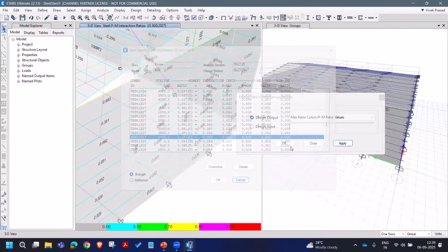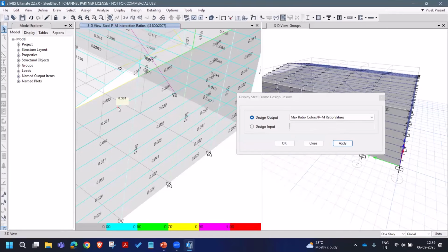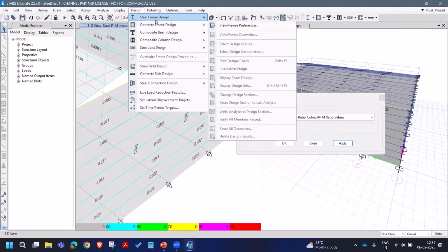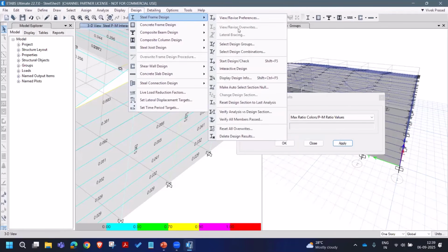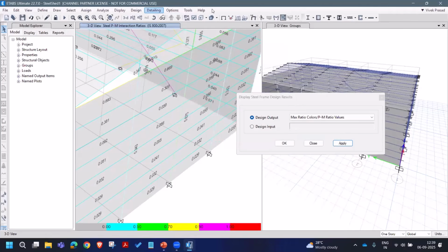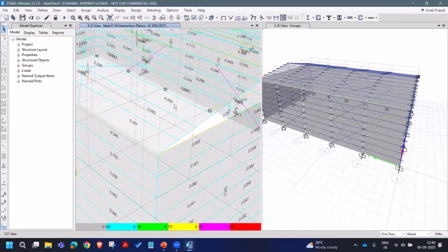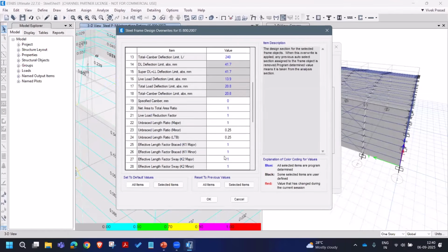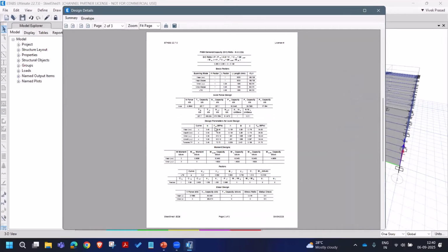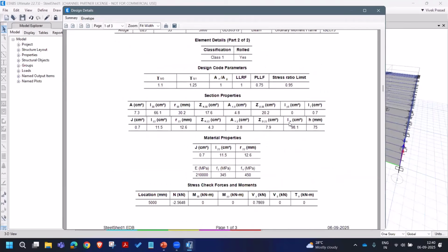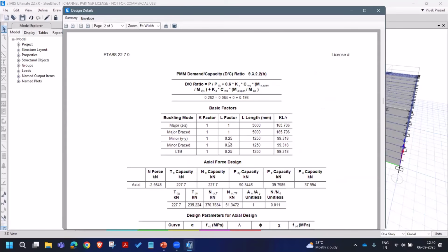Right? So overrides directly, there is an override available. This will apply only to the selected member. When we use the design after selecting members, you can directly view and revise overrides for selected members, right? That you should remember. We specified this as 0.25. Enter the details. In the calculation, you can see for these purlins, let's use the length factor 0.25 and 1.25 meters is used.